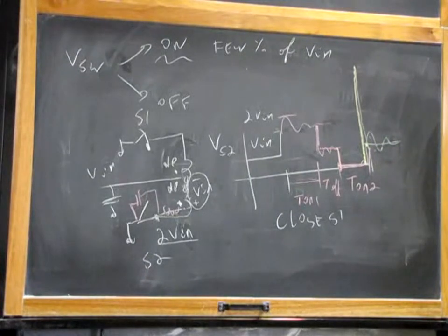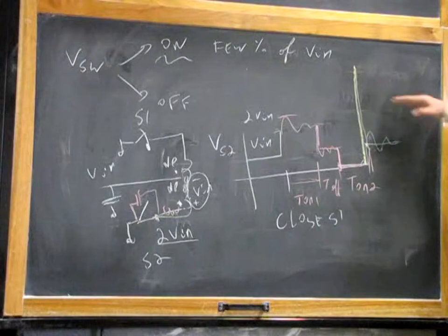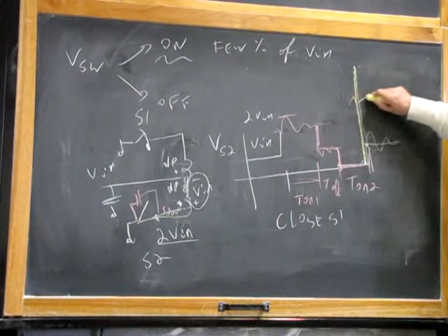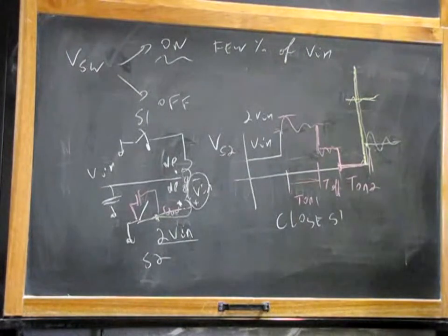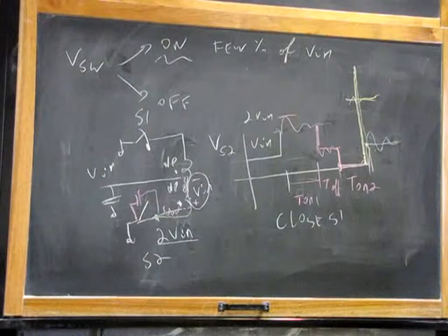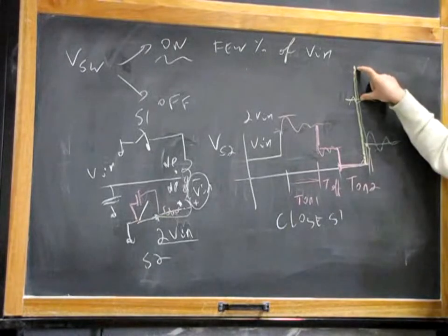This partially happened in a flyback converter, but in a flyback converter it's not so bad because it's not a high power converter, it's not a high current converter. But this overvoltage can be blocked somewhere over here using, for example, clamp diodes, Zener diodes. There's not so much energy for it here, but it's enough to kill your transistor.